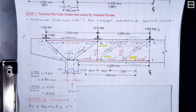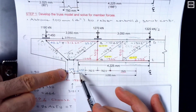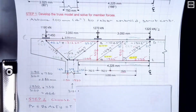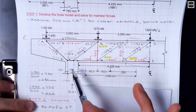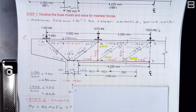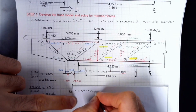I would like to add another check. We designed the pier cap, but we didn't really design the column. I'm guessing you would be using your software for column design, which, you don't need a strut-and-tie for column design, but since we finished this, let's just run a quick calculation to see the column bearing. I'm only going to be using the compression for the column, and I'm just going to do a bearing check, pretty quick, to see whether the column is sufficient or not. So this is a really quick column check.